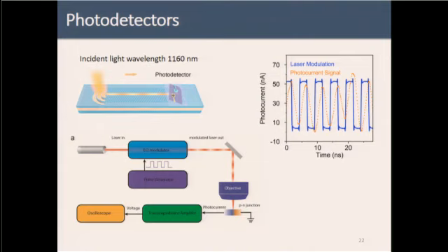In addition, this is a byproduct, but it's also very nice because, as you know, a p-n junction can also work as a photodetector. If you shine light onto this photodetector, you will create a photocurrent, and by measuring the photocurrent you get the signal that light is coming. So we started to shine a laser into our device. We have an electro-optical modulator, which can be used to add a signal, so we modulate the light, and the detector gives us a modulated photocurrent response.